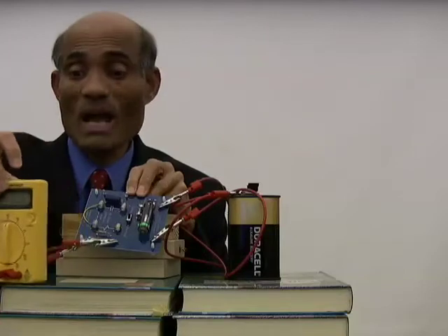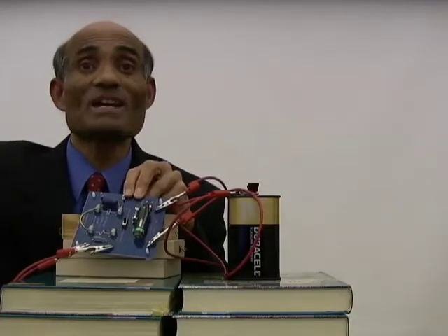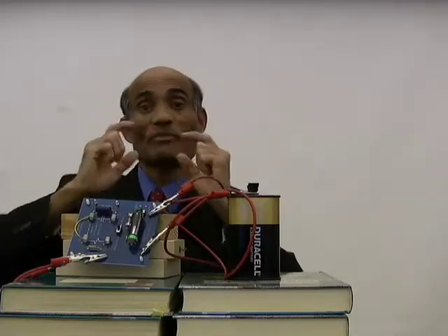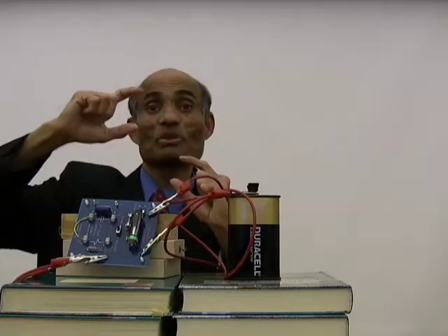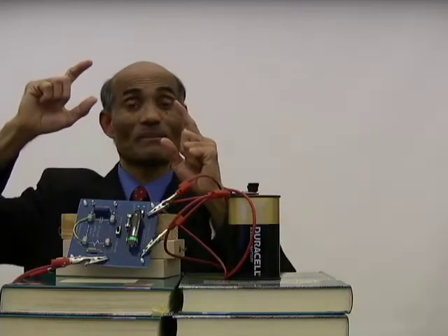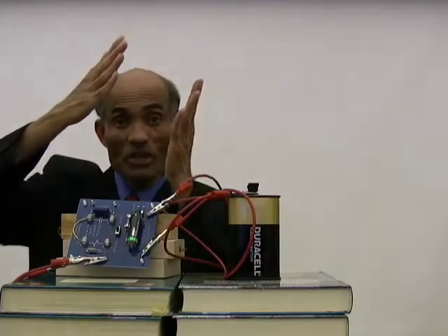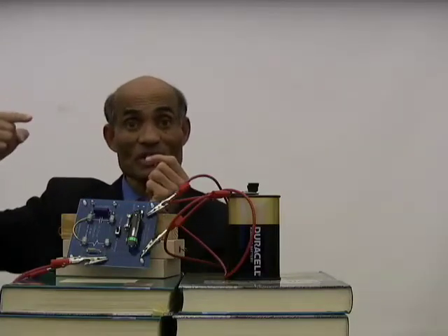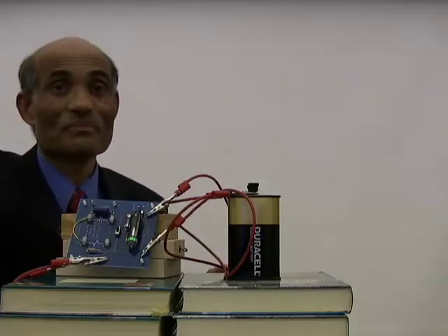So this is what happens when you charge a capacitor. The amount of charge on the capacitor plates increases, thereby increasing the potential difference across the capacitor. And the current in the capacitor decreases. That means the current in the resistor decreases. And that's the reason why the potential difference in the resistor decreases. Voila. Let me see if I can show a similar thing on the computer.